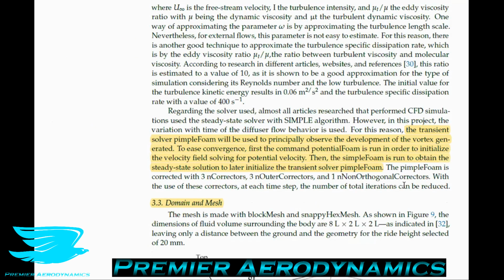So let's talk about the setup. They say that the transient solver pimpleFoam was used to principally observe the development of the vortices generated. So pimpleFoam is the unsteady RANS solver for OpenFoam. This is different to something called simpleFoam, which is the steady state version. And so pimpleFoam and simpleFoam are the two different ones for RANS. They're using the pimpleFoam here ideally, which means that they're using unsteady.